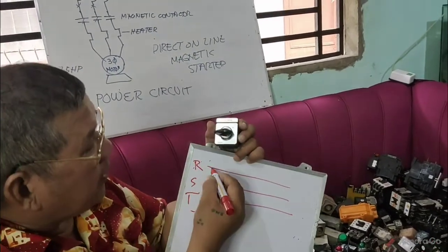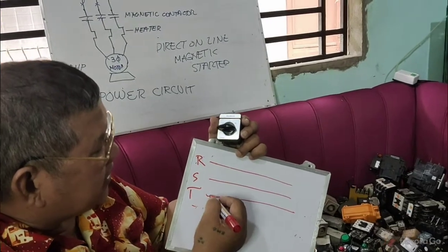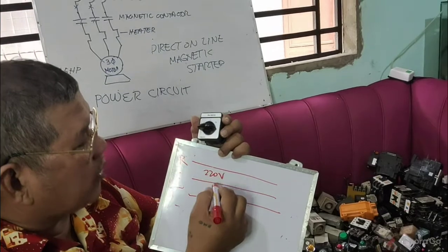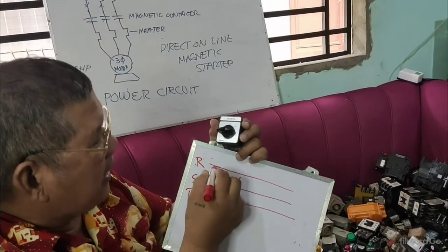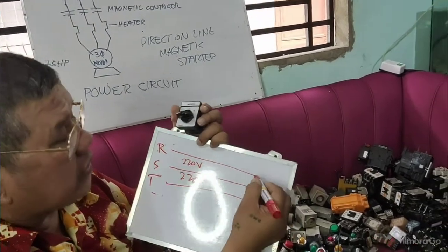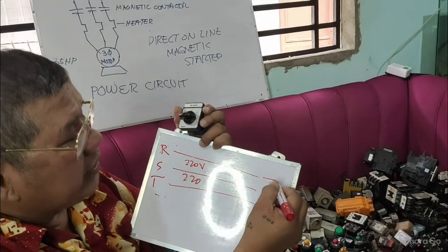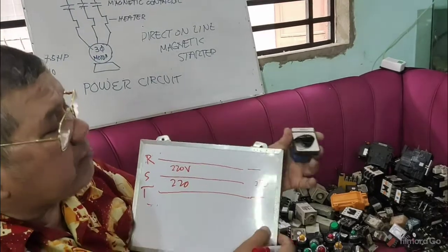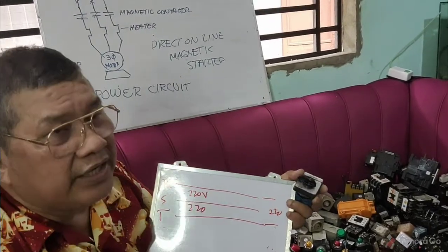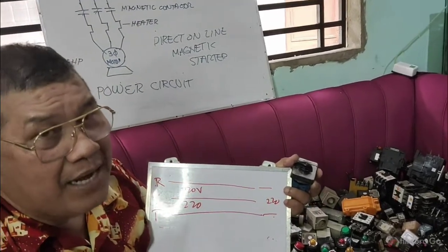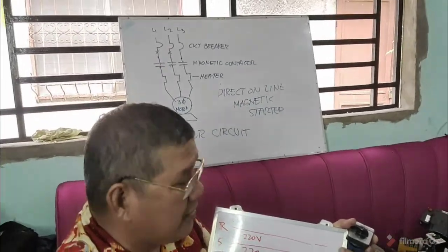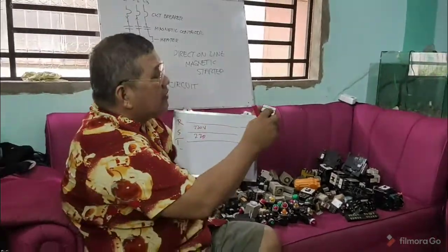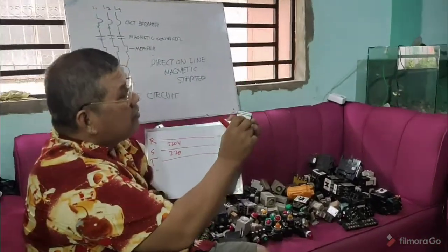Okay? So we have here RS, you have here ST, then you have RT. Now remember, every phase is rated 220 volts. RS 220, ST 220, then RT, also here, is 220 volts. Then if I'm going to test, because in three-phase, it should have a balanced voltage in every phase. So if I'm going to test the RS, I will just simply adjust this. Put that to RS.